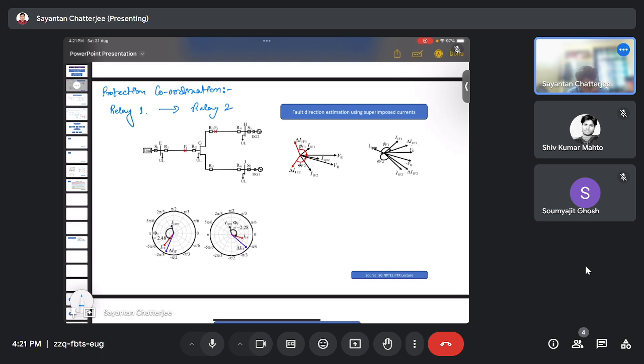So here, the positive sequence current based adaptive protection scheme selects. Suppose here we have a fault F1. Based on the fault on F1, there can be cases where this DG as well as this DG would also participate in this fault. Our main aim now is to disconnect these two sections. These two relays should operate to disconnect this section. But if sometimes it can't operate, then we'll have to go for backup protection schemes.